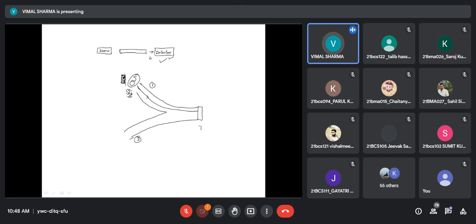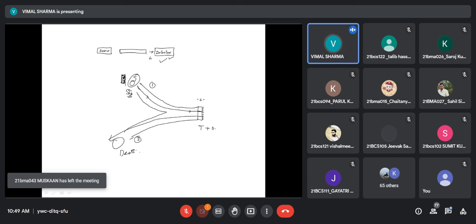At different temperatures, a different amount of light is absorbed by the silicon. And here we have placed a highly reflecting mirror, so whatever goes through the silicon is reflected back again. So light travels two times through this silicon. If there is no change in the temperature of the silicon, the intensity of light detected by the detector will be the same every time.